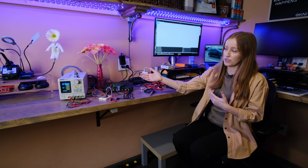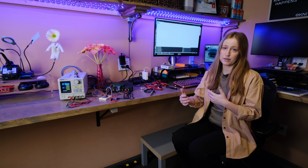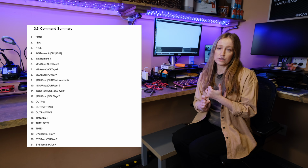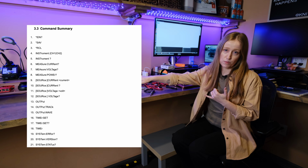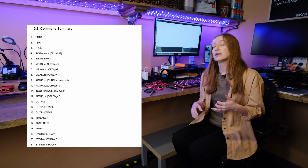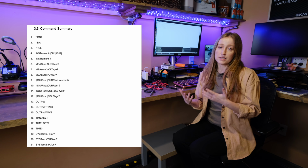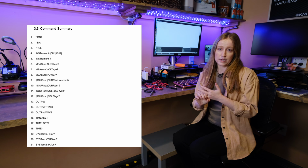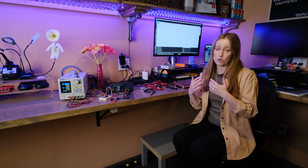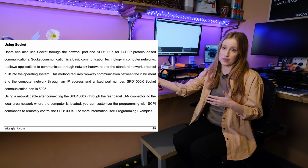So when you choose an instrument like this, it will come with a user guide that will show you all of the commands that are related to each action. Every button that you press on it has a corresponding SCPI command to execute it remotely. And because it's a network connection, it's just a socket that's opened. The user guide will also tell you which port the socket is on in the instrument.